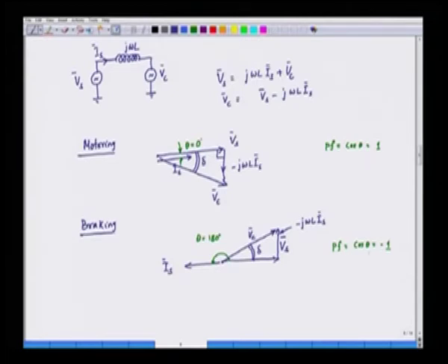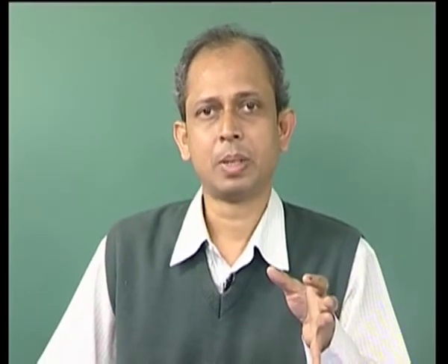For the motoring the power factor is +1 and for the braking the power factor is -1. So, if we think about a closed loop control, primarily we will be talking about the control of the front end converter. The front end converter is the one which maintains the power factor unity, and hence it ensures a utility friendly drive system.